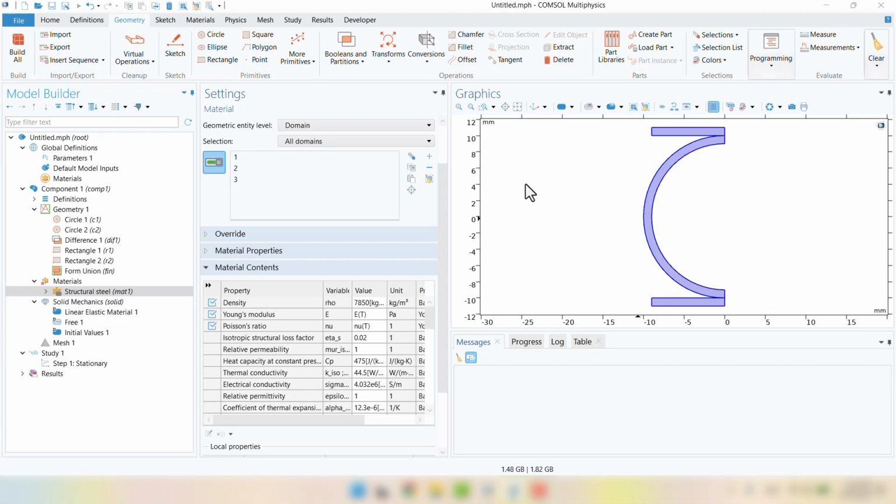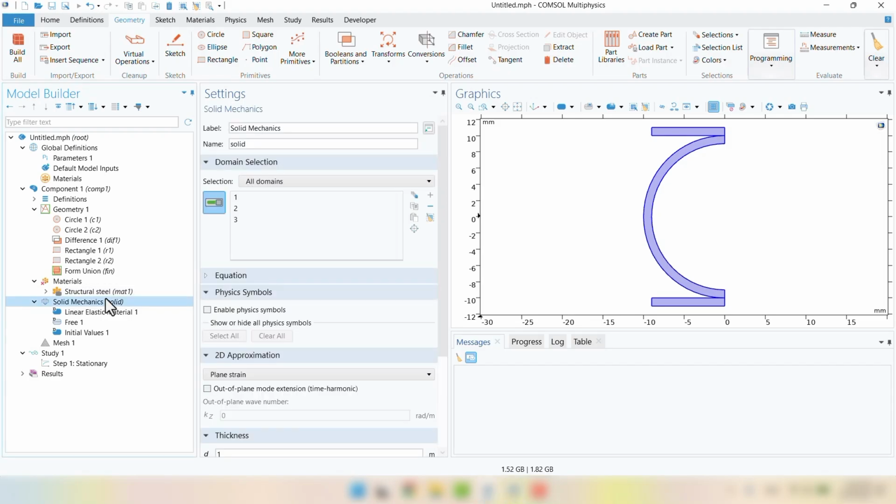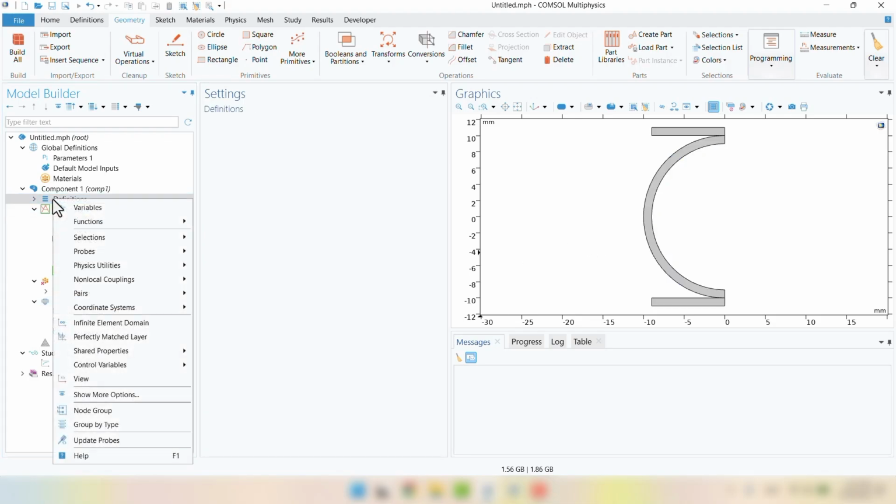Before adding the boundary conditions and configuring the solid mechanics interface, I'd like to define the contact conditions between the 2 jaws and the tube. At the moment, the geometry is still created using the union operation, so the domains are already bonded together. However, I include this setup for later use when switching to form assembly. I right-click on Definitions, then from Pairs, I select Contact Pair.